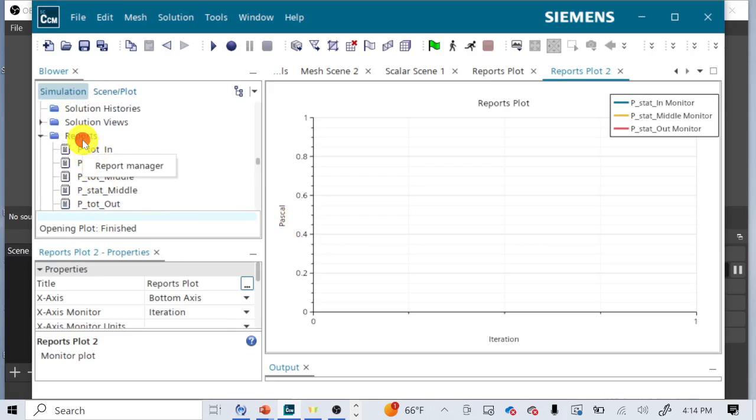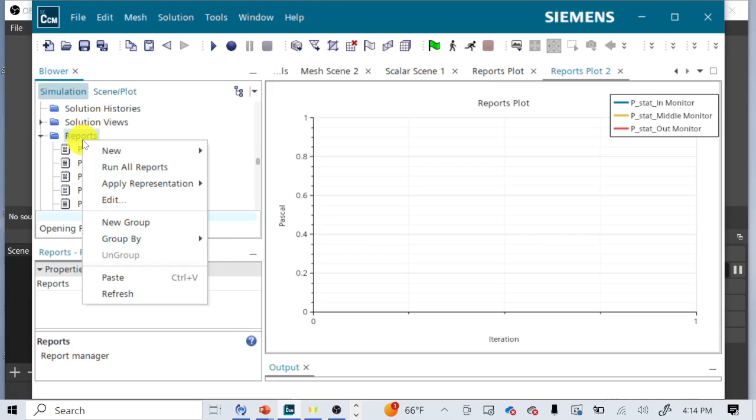Now, volumetric flow rate. How do we measure that? Any ideas? Anyone remember anything about continuity, AE160? Okay, mass flow rate's close. How do you calculate mass flow rate? Rho times V times A, assuming velocity is normal to the surface and the surface is flat. It works out to this basic equation.